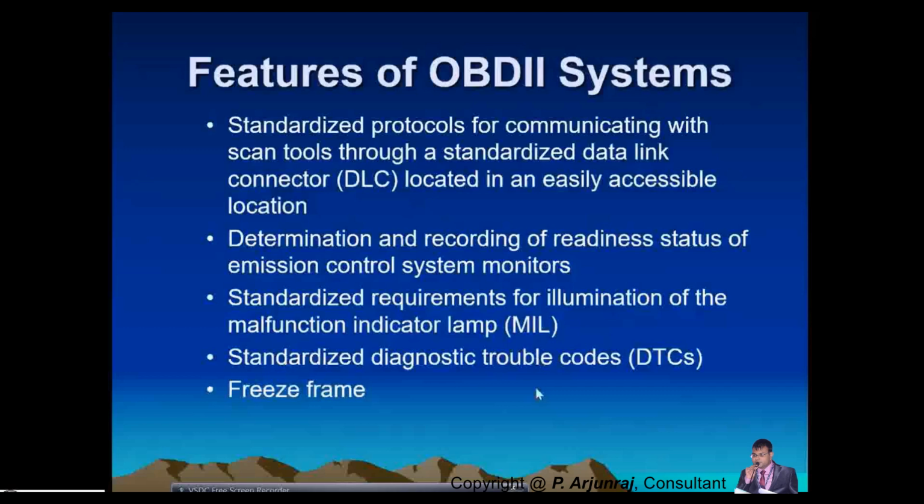The other feature in onboard diagnostics is DTC, which stands for diagnostic trouble code. You have a lot of codes. You have separate codes for engines, frames, chassis, body, brakes. With respect to the particular code, you get the trouble code, and not only that, you can also find out some of the solutions, on what basis you can eradicate that particular problem using the code.